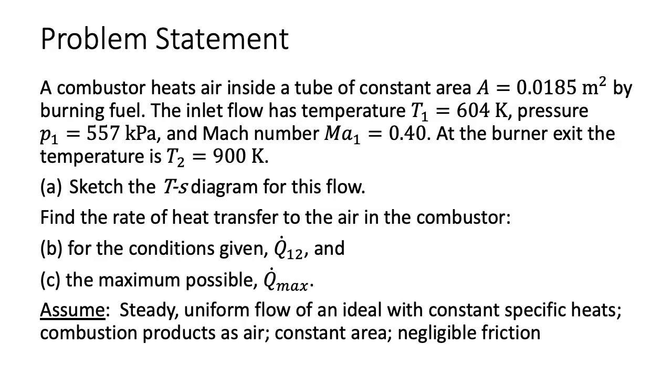For this problem, we will assume steady, uniform flow of an ideal gas with constant specific heats. We will also assume that the combustion products can be modeled as air. Finally, we will assume constant area for the tube with negligible friction.